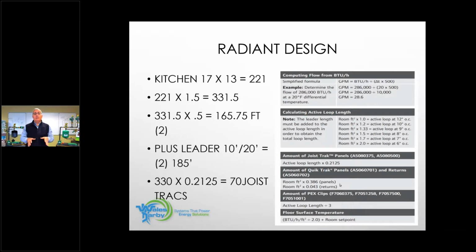All right, so we're going to insulate under that kitchen floor. If we don't, the BTUs are going to go up and down. All right, everybody see that? The BTUs will go up and down. So what will happen is we'll be fine on a mild day. And then boom, overnight we hit design temperature or even less. And now that room can't keep up because I'm losing BTUs to below.